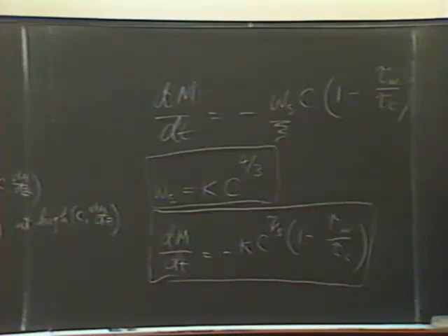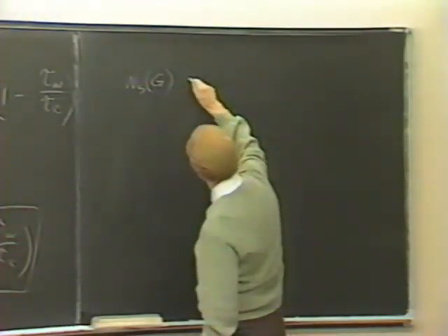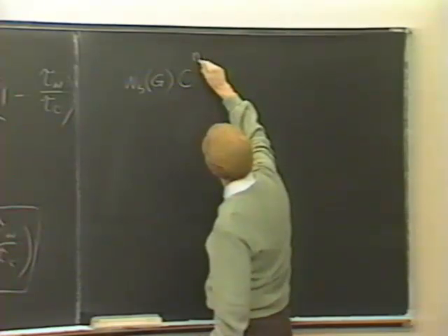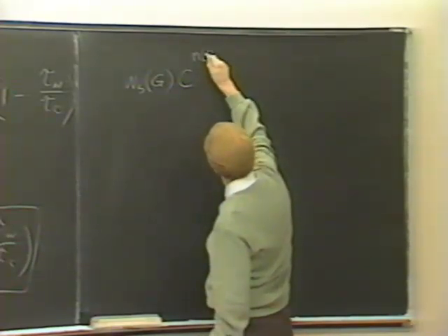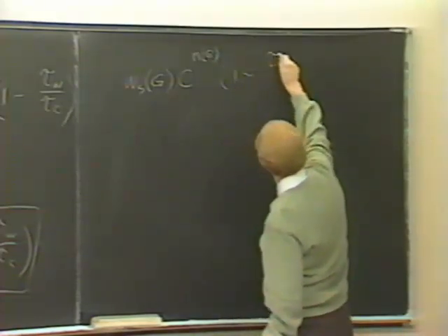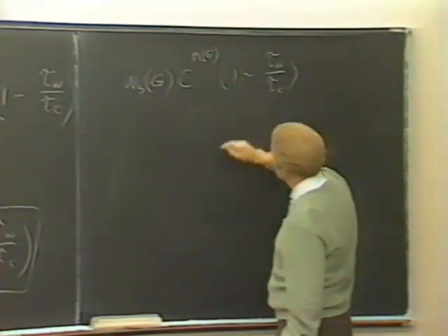There are two other ways to use this relationship in deposition computations. One is to examine the hydrographic surveys of a harbor or some area of concern that you're trying to model, and determine the rate of deposition over a period of time, say 3 or 4 or 5 years, typical.